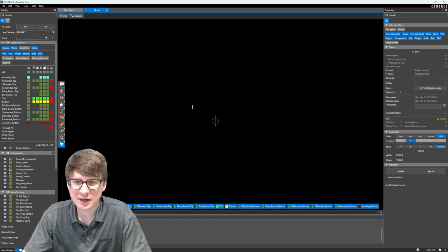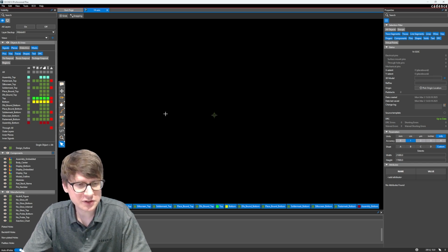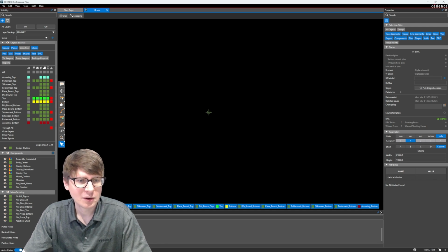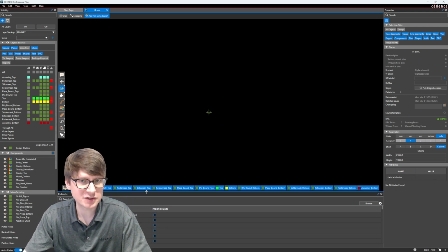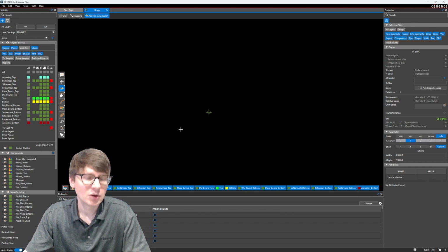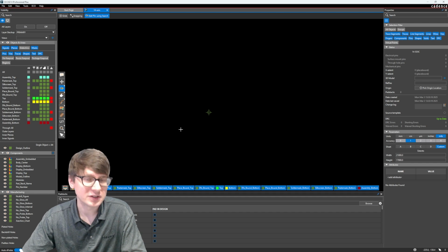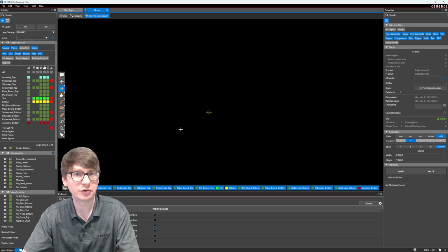All right, so the first step we want to take is we want to actually add some pins to our footprint. Again, 2 ways to do this, as you'll often find with OrCAD X. There's a couple different ways to do things. One is we can add pin using search, meaning that if we've already created a pin which matches the dimensions which are specified by the data sheet, we can then reuse that pin maybe between SOIC footprints. Maybe you're reusing pins between like a 0603 capacitor and an 0603 resistor, whatever it might be. If you've created it before, feel free to reuse it.